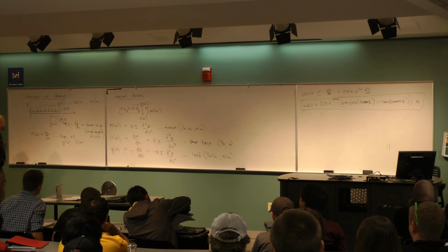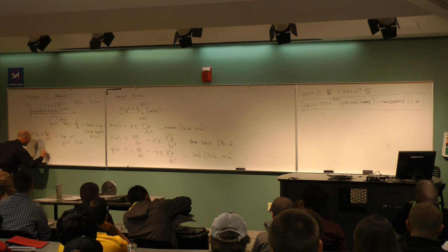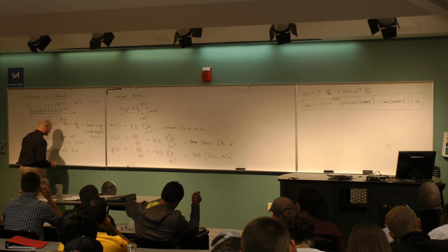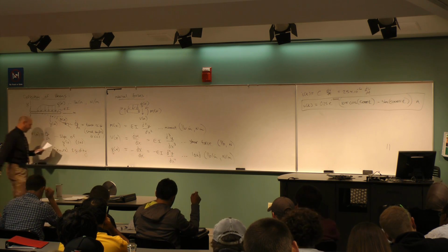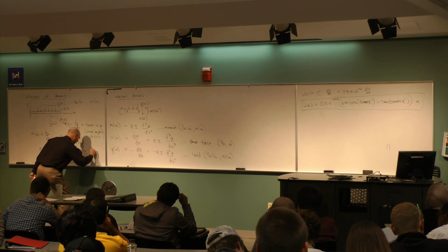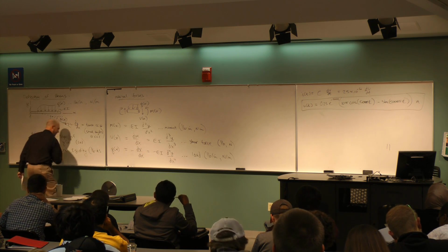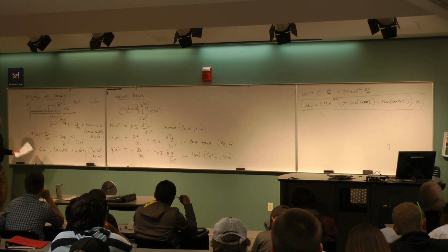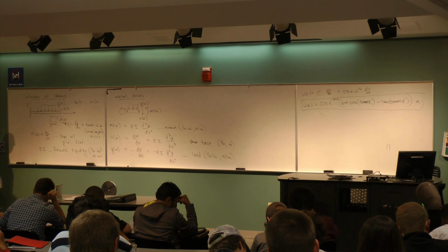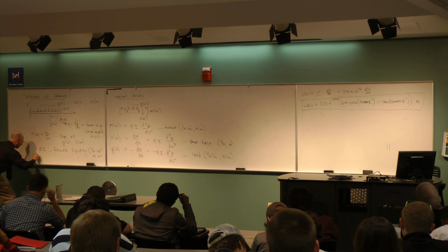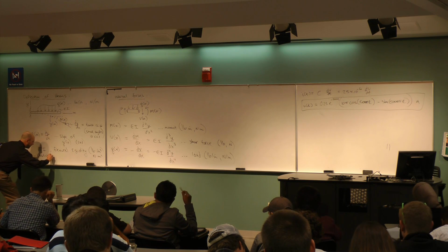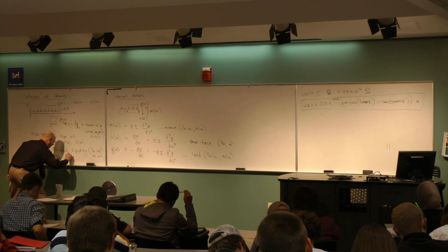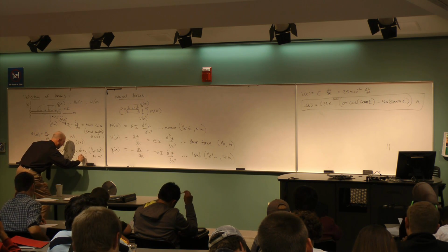Okay, and so finally, I guess the one thing I will define for you is the EI. This is called the flexural rigidity of the beam. This is in pounds times inches squared, or newtons times meters squared, would be the units for that. And each of these things is a different property, right? So E is called the elastic modulus. That is a property of the material itself, and that is measured in either pounds per square inch or newtons per square meter.